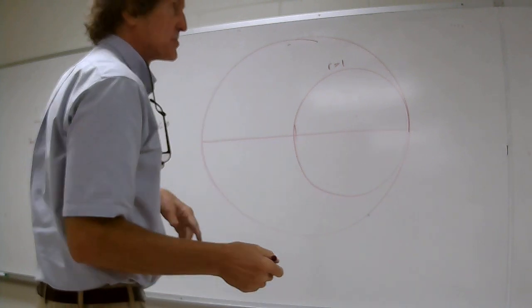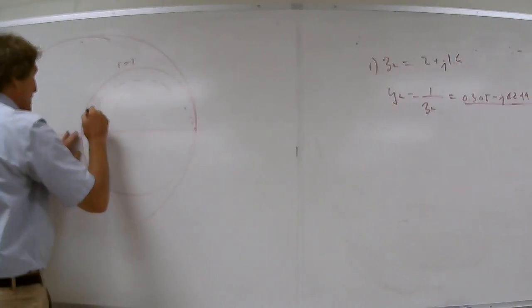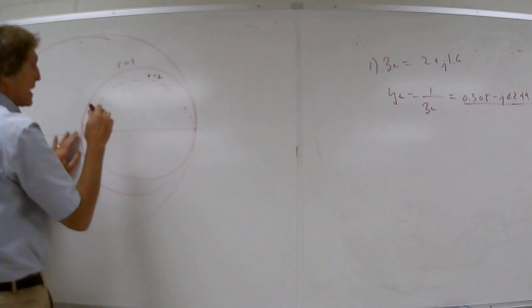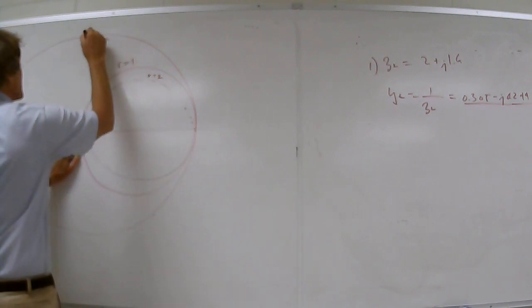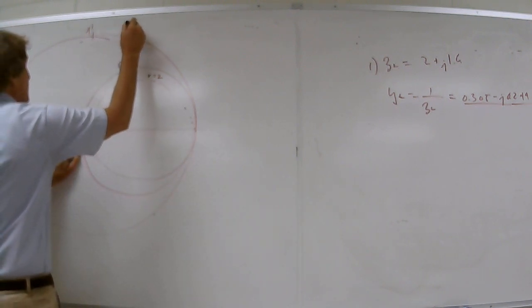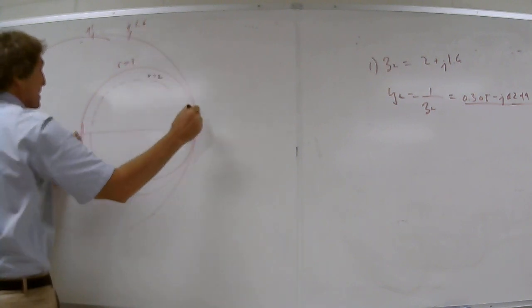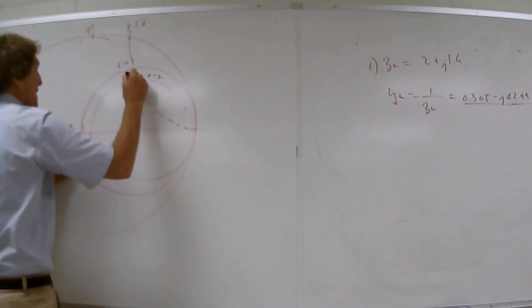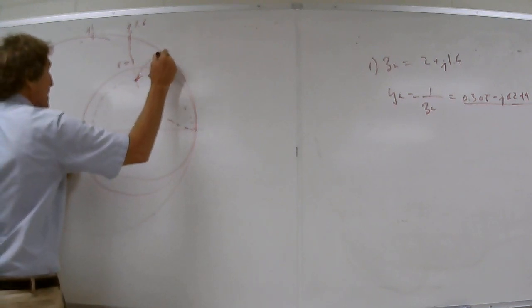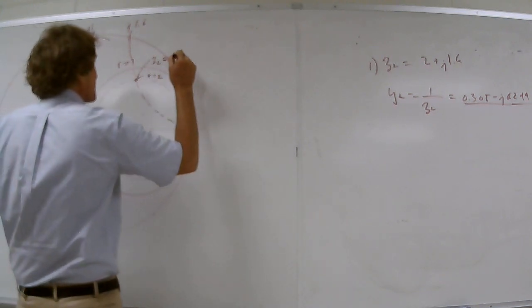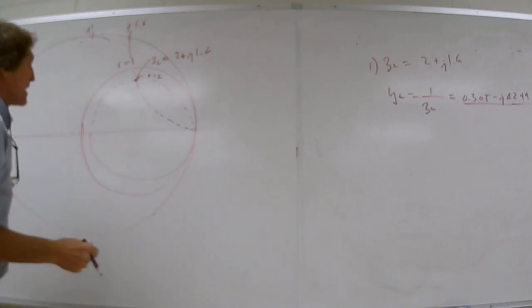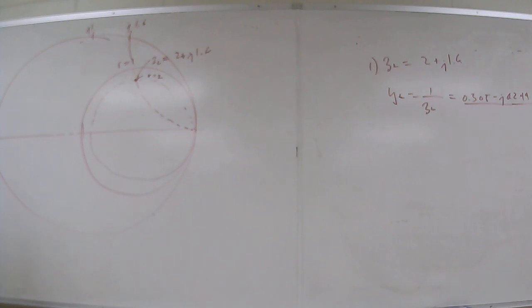Now, you can also do it this way, and I do it this way all the time. 2 plus j1.6: 2 is about here. Take a look at your Smith charts. That's about R equal 2. And 1.6, well, this is j1, 1.6 is about here. So you see where these two points meet. This is going to be ZL, which is 2 plus j1.6. Y'all with me?